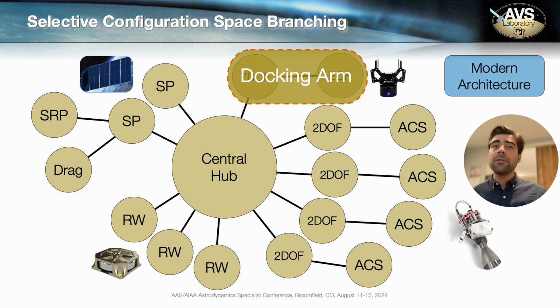So one of the benefits of the back substitution method is that currently if you model a reaction wheel or a thruster or a solar panel, you can dynamically add and subtract these components to your spacecraft without having to rederive your total spacecraft equations of motion. We want to continue to be able to do that, but now with branching components.